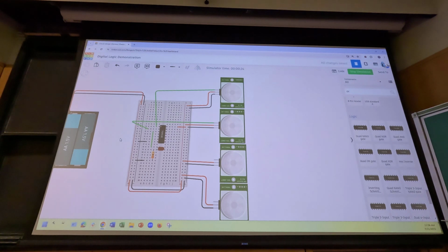Okay? So if you were stuck, try to at least get that far, and then see if you can change things such that the LED will turn on if any of the sensors detect motion. Remember, this chip has 4 OR gates in it, so you should not need a second chip.